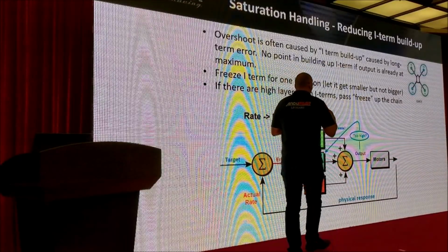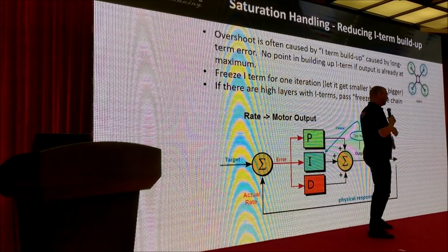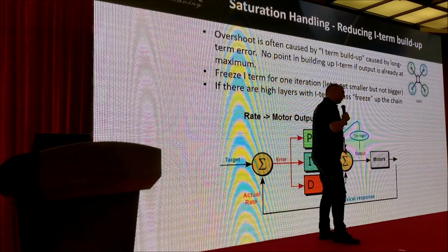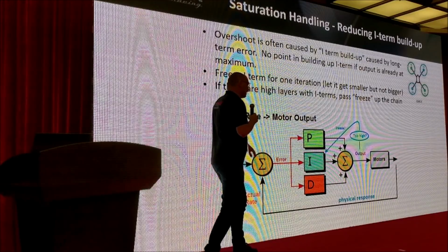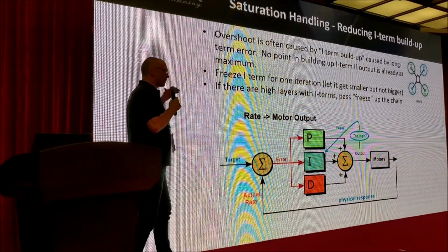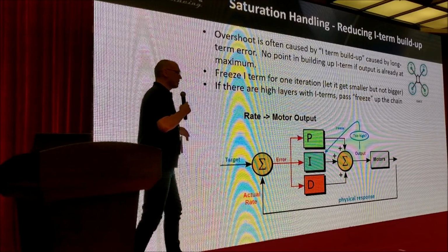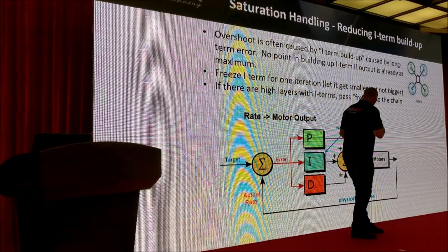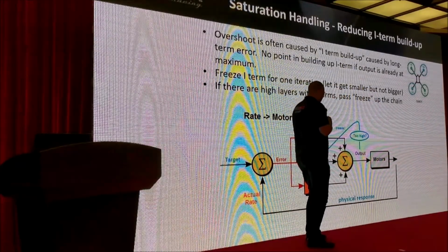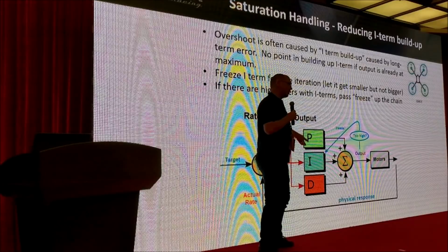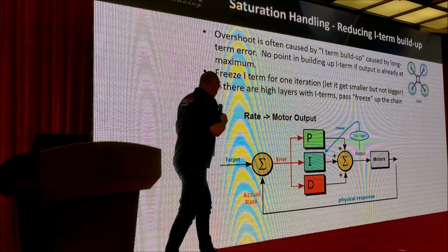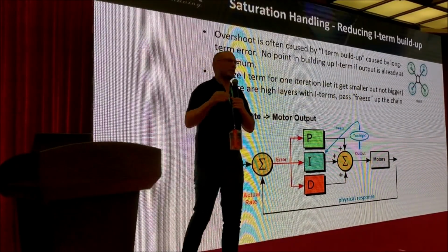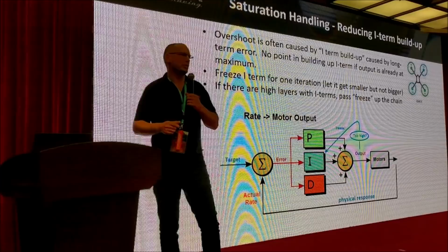So to stop that, we have a number of features that allow the motors to communicate with each level of the PID controllers and up through the navigation controllers and all of the other controllers that sit above this, so that when the motors are saturated, we deal with that saturation in the I-term. We may reset some parameters. We deal with it at the higher levels. We don't ask for a change in velocity or an increase in velocity in the navigation controllers.